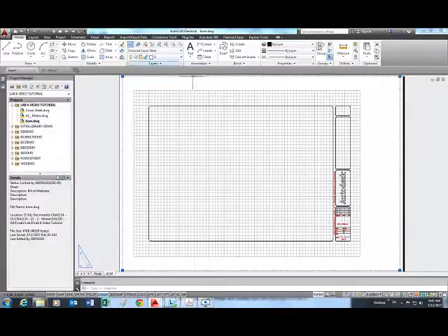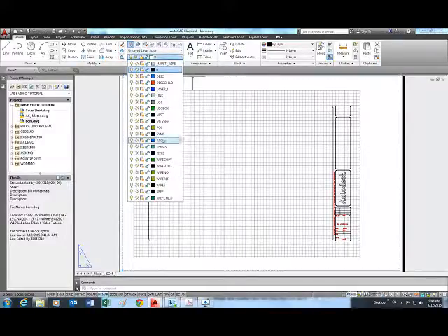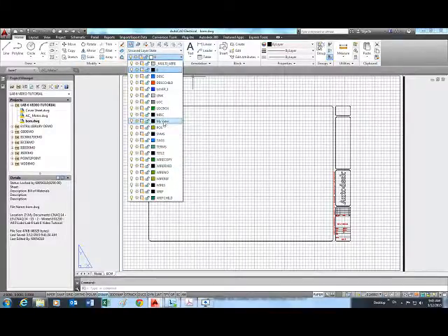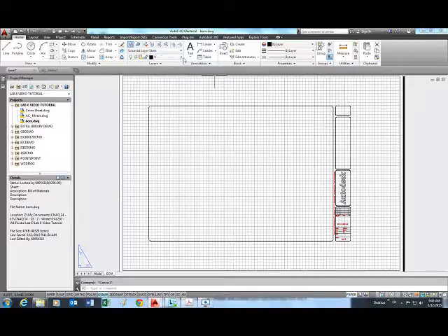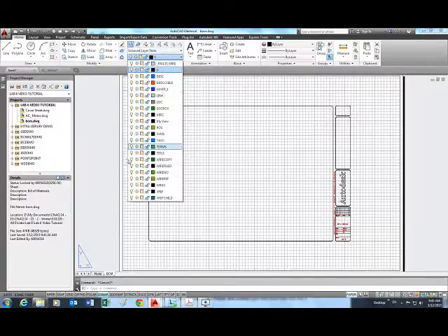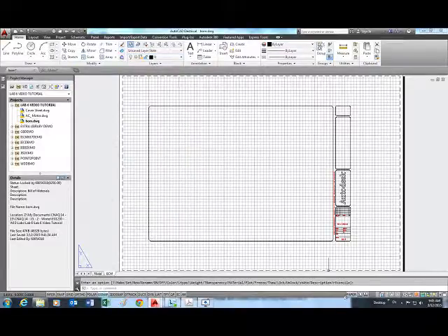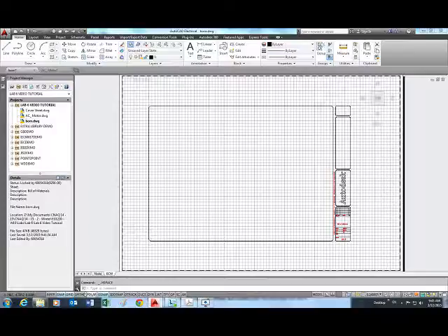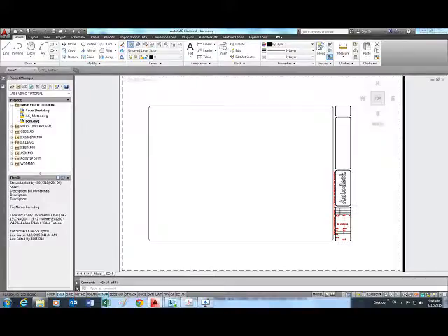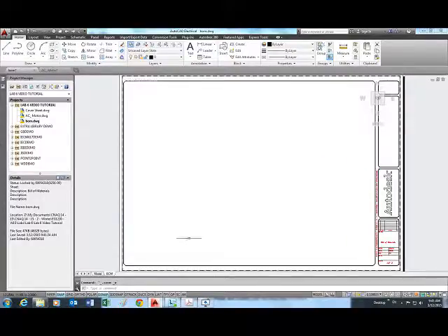Go to the viewport, make sure it resides on my view layer, escape, turn off that layer so that the frame of the viewport does not print. Okay, let's go to model space, turn off the grid, double click the wheel, zoom extent, and let's turn off nav cube. Okay, and then again save.